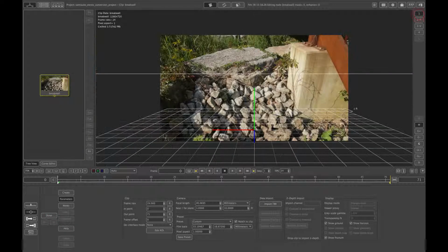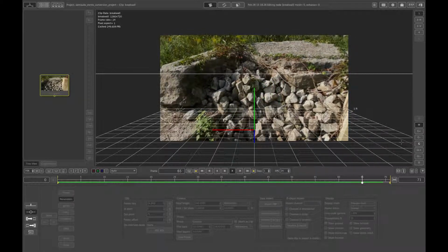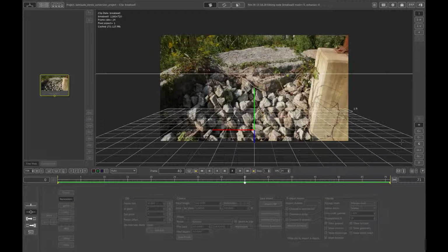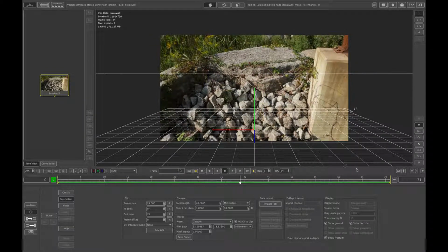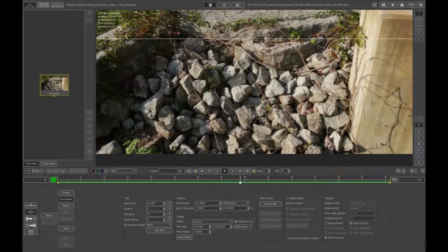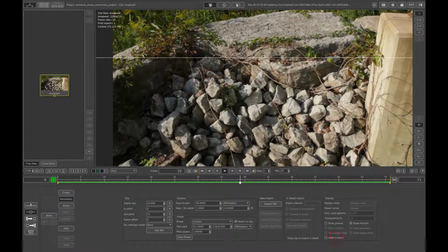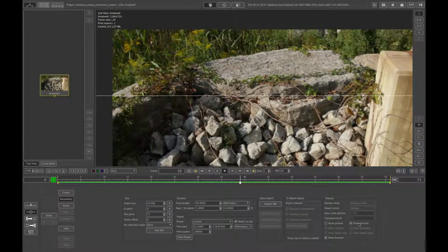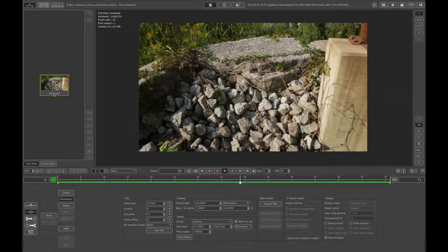And some of you may have seen this shot on the website already, but I'm going to take you through all of the steps to do a semi-automatic stereoscopic conversion on this. As I mentioned once before, it would typically be a difficult shot to work on, basically because of all of the occlusion that's happening in here. We've got all of these rocks, we've got grass, we've got twigs overlapping things, all kinds of stuff going on in here. So to try and rotoscope this would take forever. So what we want to do is try and automate as much of the process as possible and get results as fast as we can, and therefore we can be more productive.